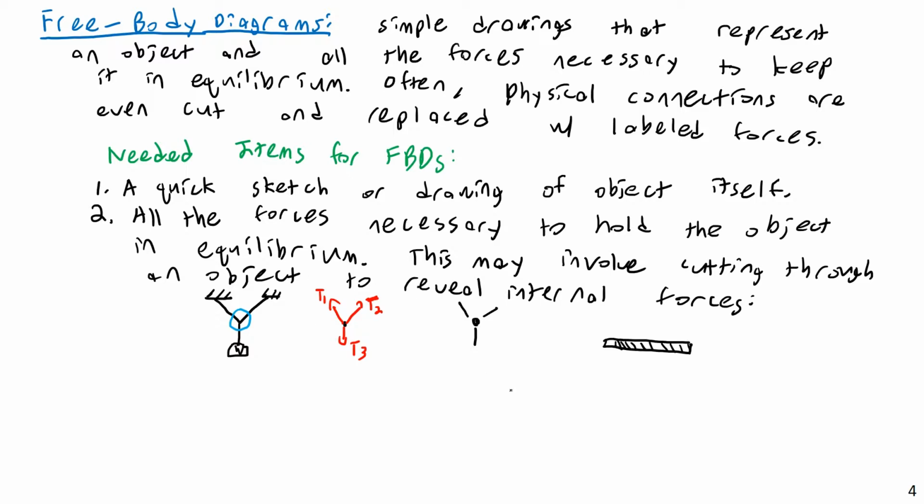Now, that's a bit absurd, but it does reveal what I really think a free body diagram is supposed to illustrate. It's supposed to illustrate that if I could magically create forces out of nothing, not going through a rope or a surface or an electric field or anything like that, literally forces from nowhere, what kind of magical forces would I need to apply to an object in order to keep it in the same position it currently is? And that's really what we're drawing with a free body diagram.